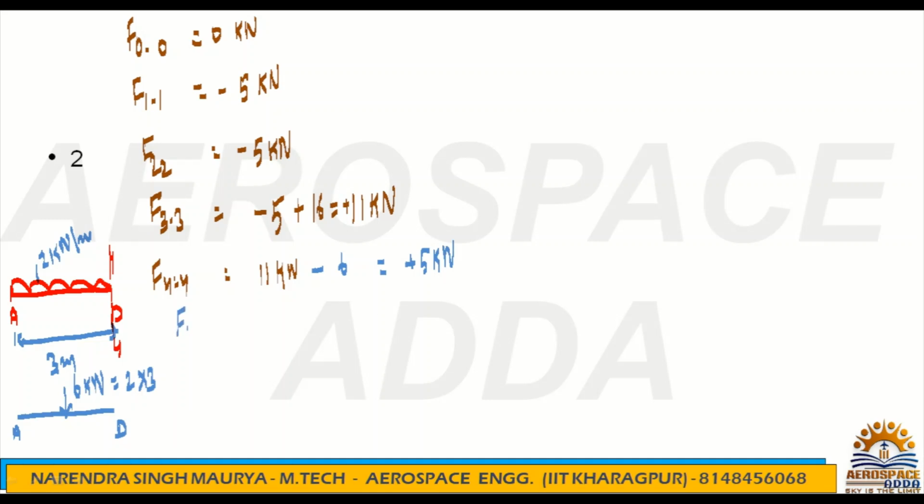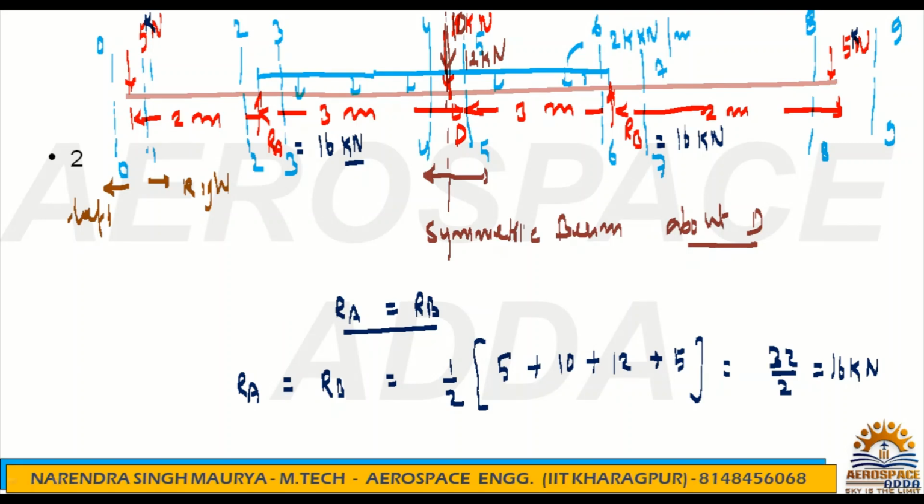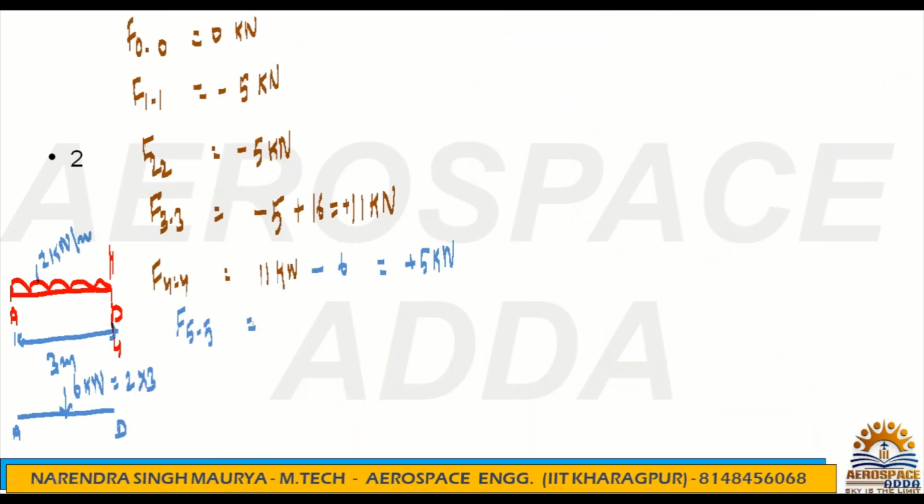Now F55. Where is the F55? Once you talk about F55, then this 10 kilonewton point load is also there, and it is in downward direction. So you got 5 kilonewton here, then minus 10, it becomes minus 5 kilonewton.